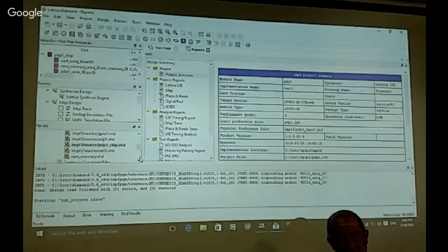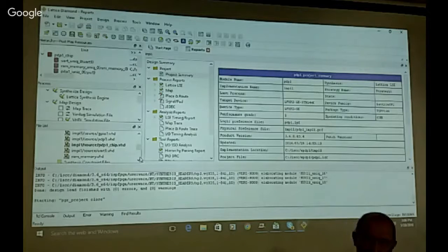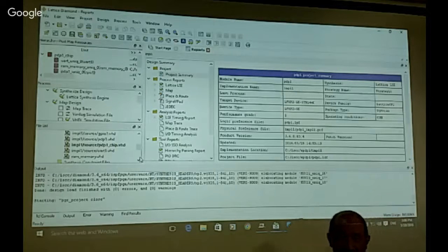They can skip on positive, skip on 0, skip on non-zero. You can skip over lots of different things, but it's all one instruction. You can also rotate or shift all different things, but it's only one instruction, with bits specifying whether it's a left shift or right shift, shifting the accumulator, shifting the IO register, or shifting them combined.